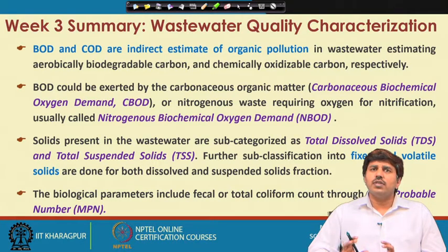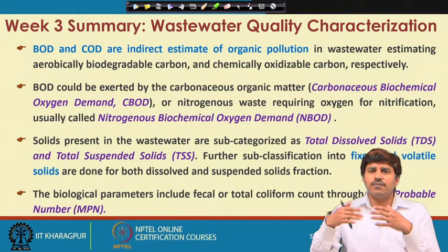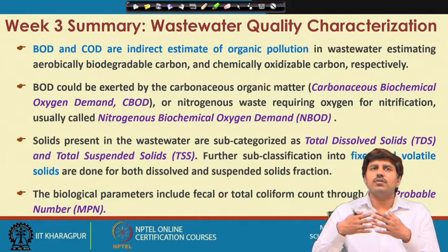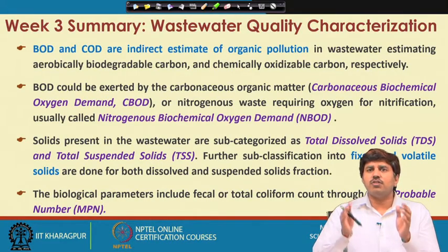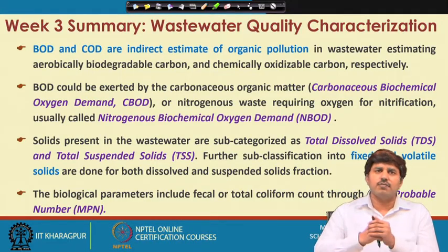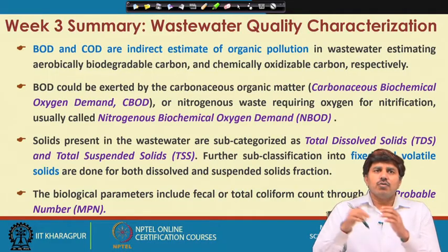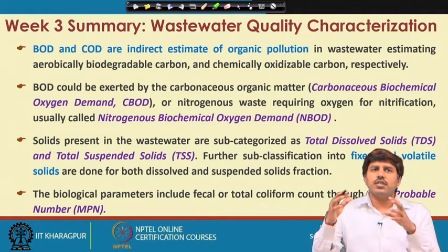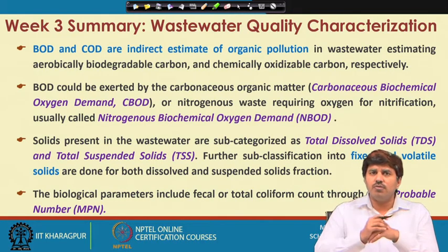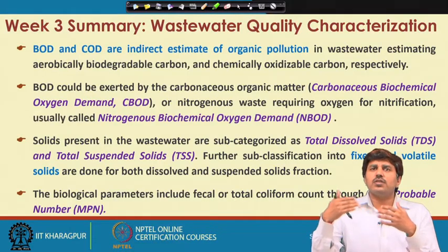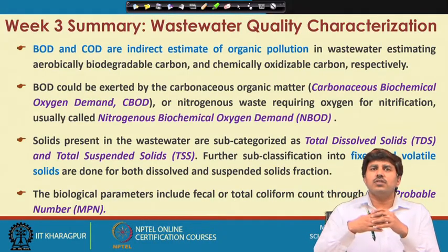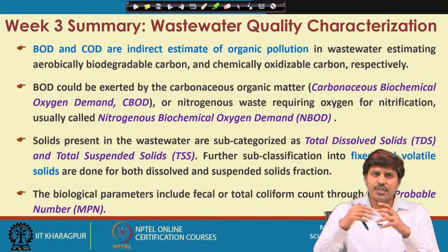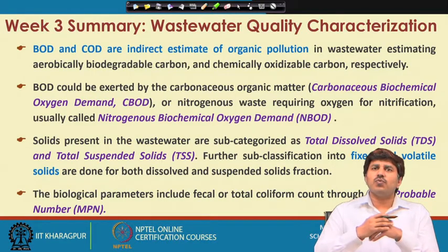So, COD is in fact always greater than the BOD values, because BOD is just an estimation of biodegradable organic carbon, whereas COD, whether it is biodegradable or non biodegradable, covers both. The BOD could be exerted by the carbonaceous organic matter, which is the carbonaceous biochemical oxygen demand, or CBOD, or by the nitrogenous waste requiring oxygen for nitrification, which is usually called NBOD, or nitrogenous biochemical oxygen demand.